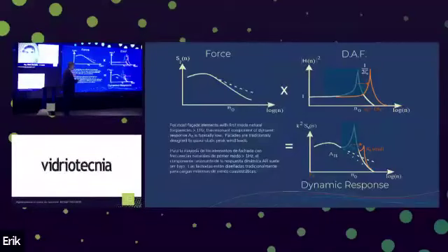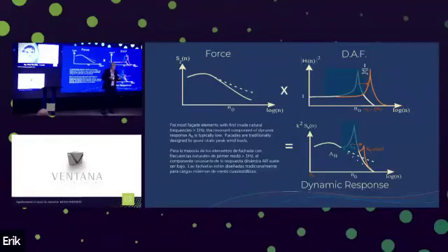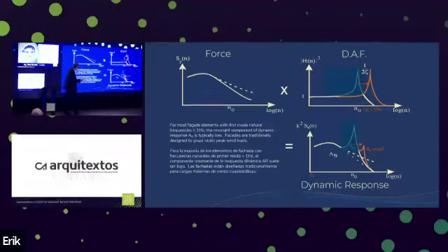Now, for most facades, conventional facades, where we're talking floor-to-ceiling spans, the natural frequencies are much greater than 1 hertz typically. So in terms of our dynamic amplification factor, it's pushed across this way where there's less energy in the turbulence spectrum. So conventionally, for most facades, the resonant component of dynamic response is small, and we can treat the load as quasi-static.